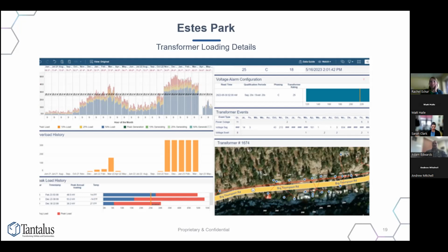I did find another instance actually on Saturday. I got a call that a transformer had failed in the middle of the night. So went out, sure enough, the transformer had failed and went back to the shop here and like, oh, I'll pull up the analytics and see what it's been doing. And it was a 37.5 overhead transformer feeding one 400 amp service, and it had no load on it.